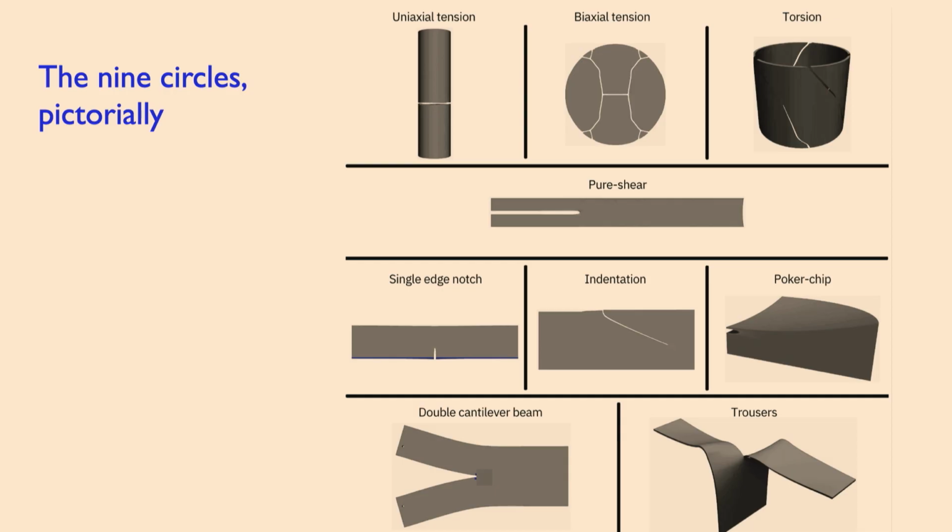Two, they lend themselves to a sharp treatment of fracture. So if at some point we have the sharp model that explains everything that we want, we should be able to apply it here. Other ones, there's already a sharp description available, right? Third, they encompass this full range of problems, right? Strength on one hand, crack nucleation, the Griffith criticality governed by energetics, mediation between strength and energetics, and then crack propagation in mode 1 and mode 3, okay?